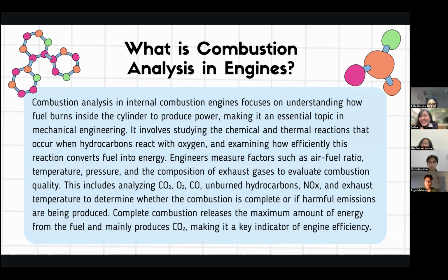Engineers measure factors such as air-fuel ratio, temperature, pressure, and the composition of exhaust gases to evaluate combustion quality. This includes analyzing CO2, O2, CO, unburned hydrocarbons, NOx, and exhaust temperature to determine whether the combustion is complete or if harmful emissions are being produced. Complete combustion releases the maximum amount of energy from the fuel and mainly produces CO2, making it a key indicator of engine efficiency.